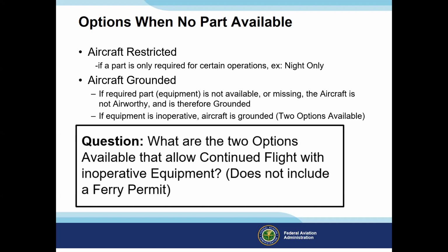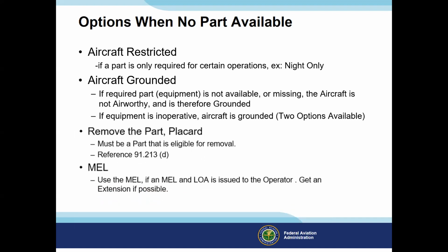Okay, so the two options are you can remove the part and placard it, deactivate it, but it must be a part that is eligible for removal under 91.213(d).